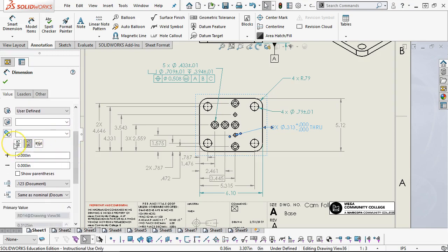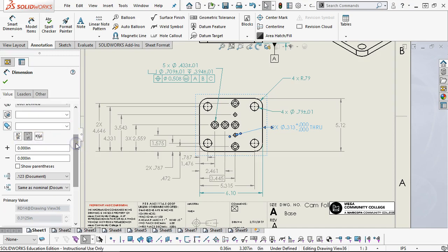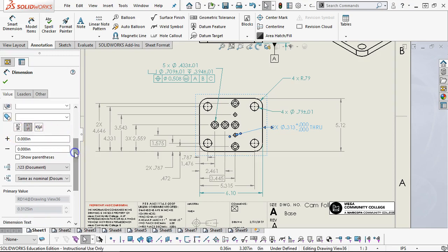So as we go through, the H value, the uppercase value, is the hole tolerance, and then the G value, lowercase, is the shaft tolerance. We can go through and relate those, and the more I look at those charts and the variation as you get to larger shafts and larger bores, it opens up those tolerances by percentage, so that you have greater flexibility in the group.